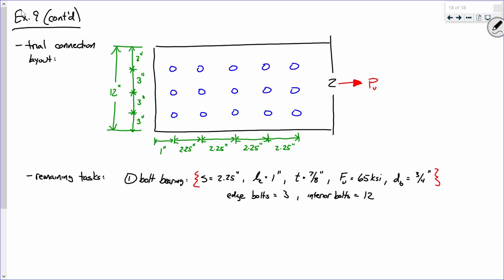We are literally just looking at the physical dimensions of that plate right there at the bolt. When we added 1/8 of an inch, we did that because we were adding a 1/16 for 2 reasons. 1/16 was added because we are physically drilling the hole a little bit larger. Another 1/16 of an inch was added because that little bit of material right around where the hole was drilled, we said, well, that's not really efficient in transferring load to the rest of the member.